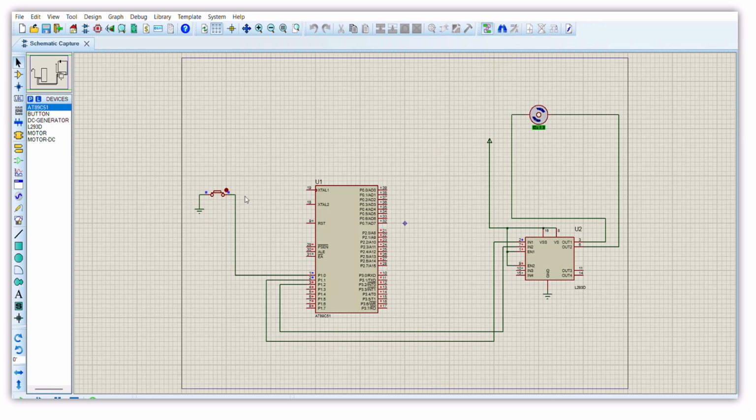1.2 to input 1 and input 2 ports of the L293D motor driver. The L293D receives these signals and controls the motor connected at out 1 and out 2 to rotate in a particular direction, either locking or unlocking the door.